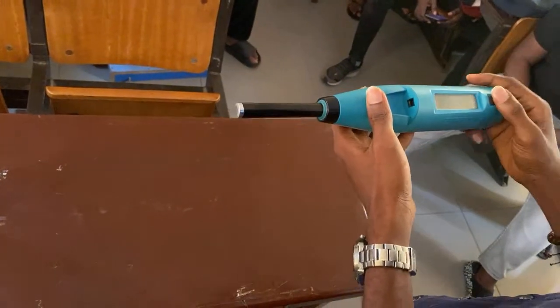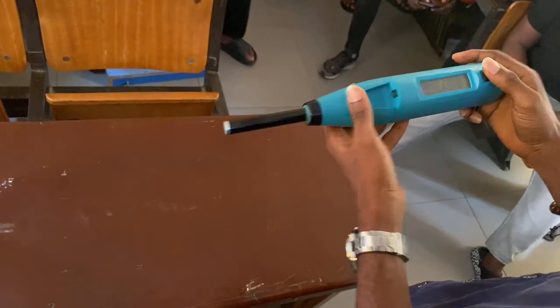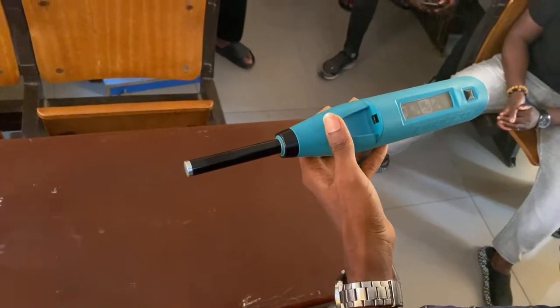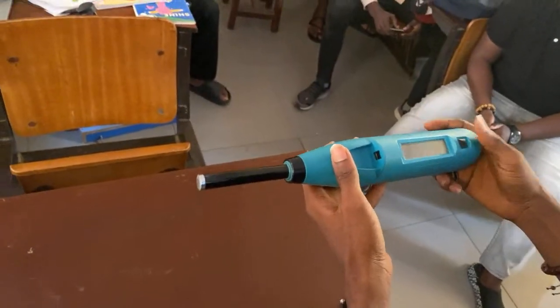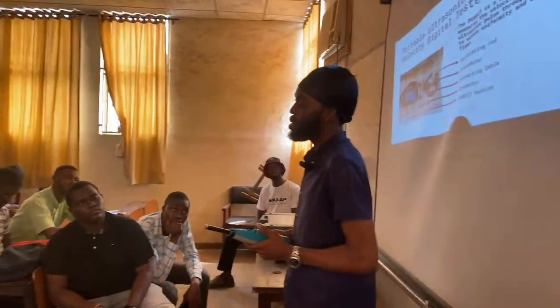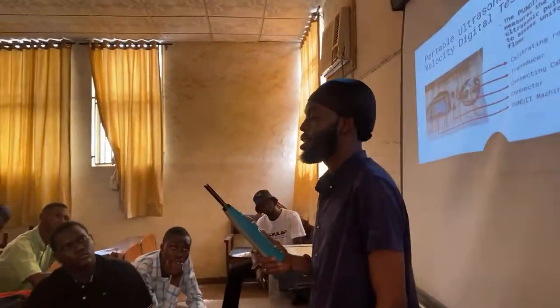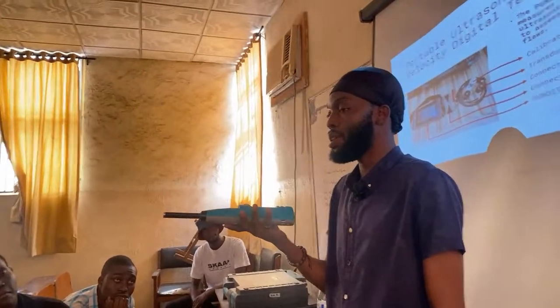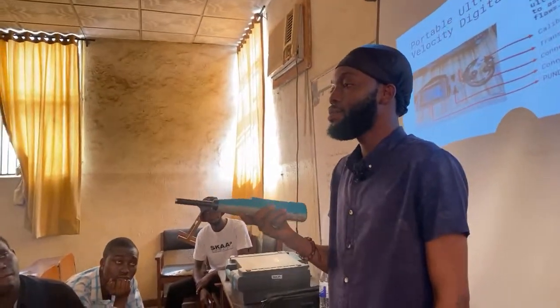Then for carbonation we also use one. For the units, we use Newton per mm square. So we select everything there. And it is said that for each test on every structural element, you take at least 9 shots. You make at least 9 impacts with the Schmidt hammer. But for a slab, we use 10.